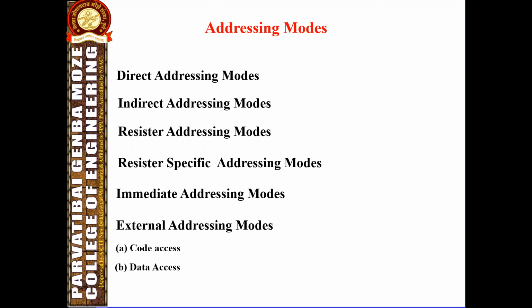First, let's see what the direct addressing mode is. In this addressing mode, the operand is specified by an 8-bit address field in the instruction.